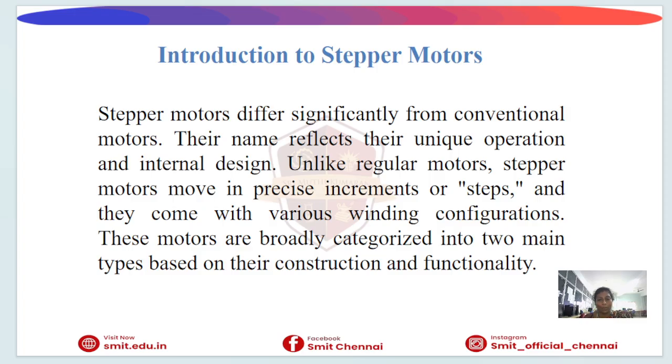One complete rotation is 360 degrees. So if the step angle is 1.8 degrees, we have 200 steps per revolution. For one revolution, we have 200 steps. So the motor requires 200 pulses to complete one full rotation. This makes stepper motors ideal for applications requiring exact positioning.